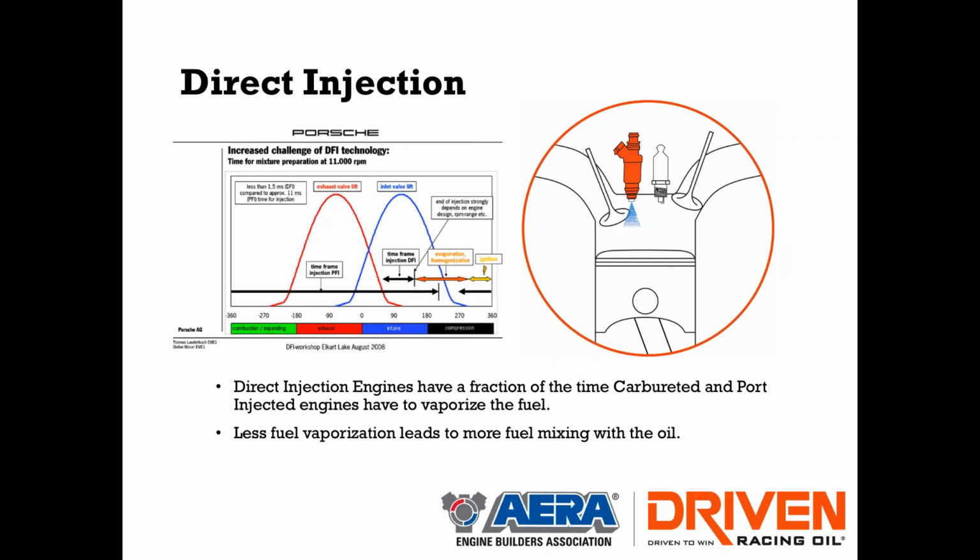When you have less time for the fuel to vaporize, especially at low engine speeds, when you have less volatility and less temperature, it's a good time to point out that in the research that's out there, it's very clear that LSPI tendency is greater at lower engine temperatures than at higher engine temperatures, which goes back to this whole vaporization issue. We talked about the oil and the fuel mixing. Well, if the fuel vaporizes, it's not going to mix with the oil.